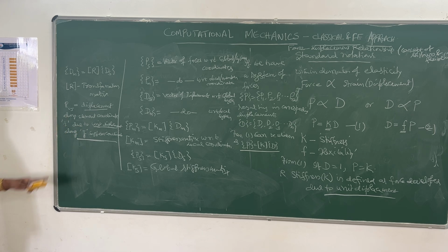You have to identify the element coordinates for the forces. You have to identify the system coordinates for forces and displacement. For displacement, system coordinates; for forces, element coordinates. Apply a unit displacement, and find the corresponding displacement only along the element coordinates, that component, that is all.